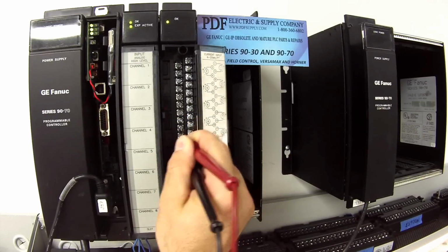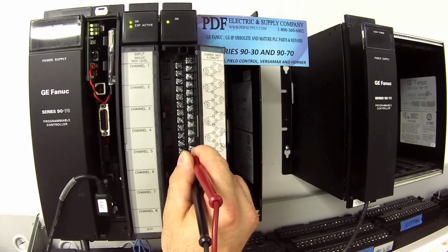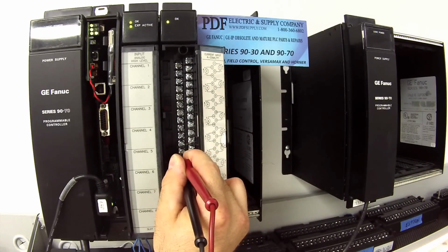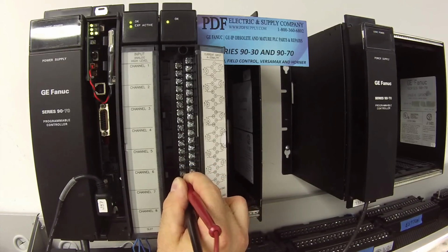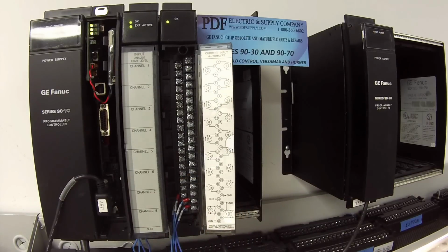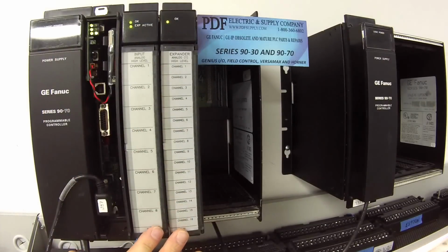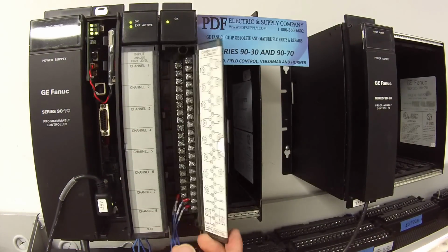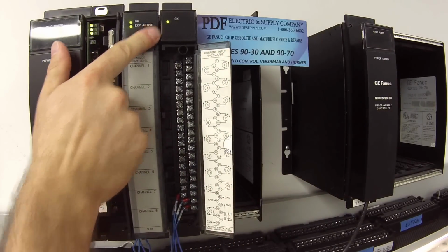I continue to test all the channels all the way through 16. So once I've seen that all the channels are working and it's in good working order, I'm satisfied that this is a perfect module and there's nothing wrong with it. The problem that I described before, if any of the channels or all the channels are stuck on full value or you don't get an OK light, are just some of the problems that you could have with an ALG440.